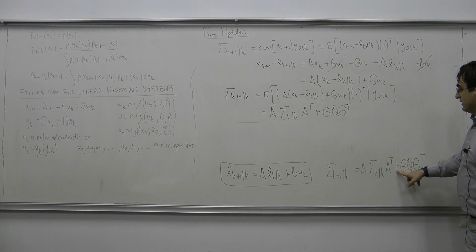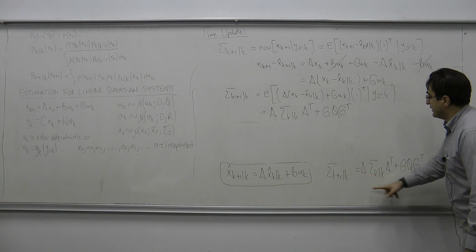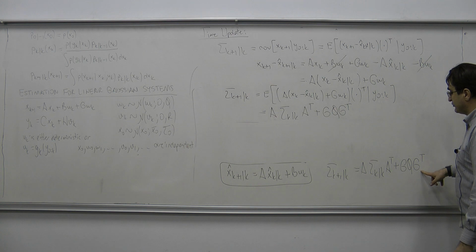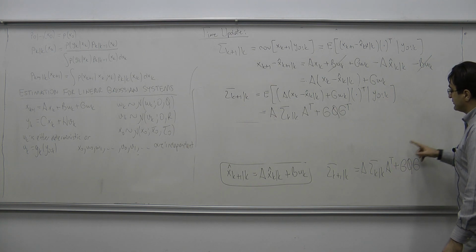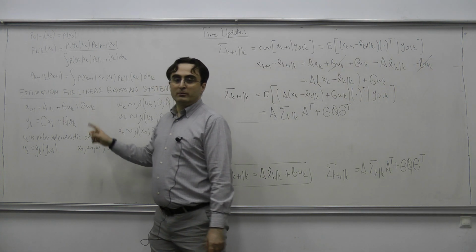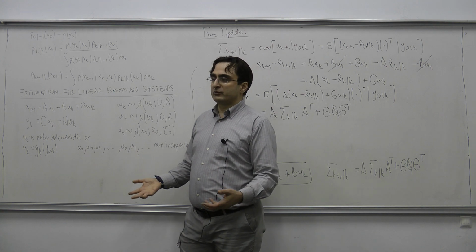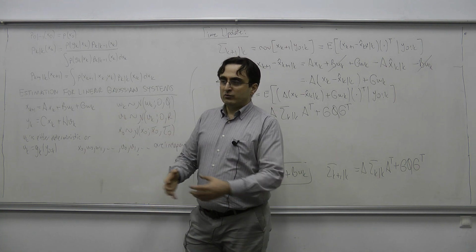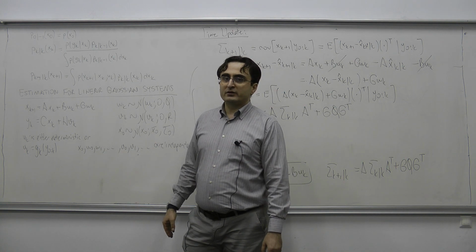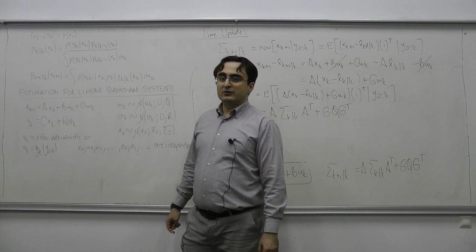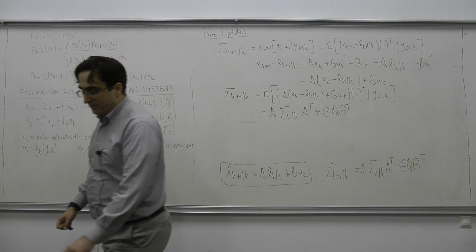This plus sign means that we are increasing the transformed current state uncertainty with GQG transpose. So this covariance increase is coming from this process noise term. Because we don't know the process noise, when we predict the future, we need to increase the current uncertainty a little bit to take the effect of the uncertainty of the process noise. All right?